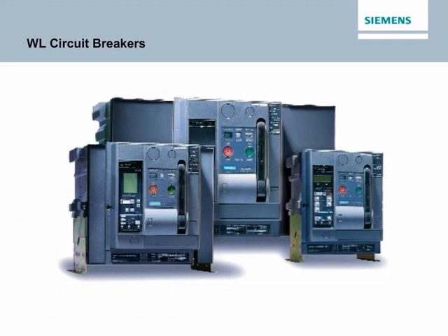This specification also covers a category of molded case circuit breaker commonly referred to as an insulated case circuit breaker, the ICCB. ICCBs are generally used in switchboards and may be fixed mounted or drawout mounted. Another category of large circuit breaker is the low voltage LV power circuit breaker.